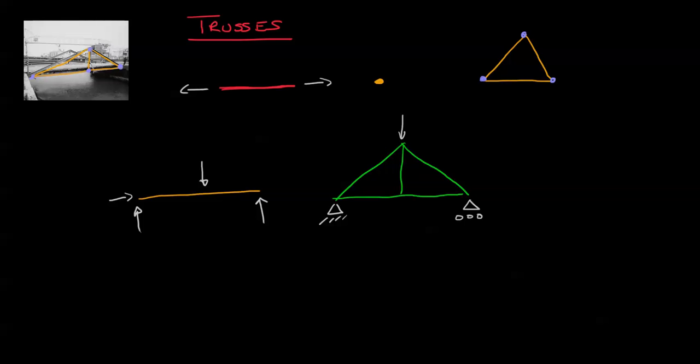And so the first thing you're thinking is, okay, well, you're applying a load. Let's do a free body diagram. So let's do a free body diagram about this point. About that point, we have the load coming in. Okay, and then from one member, we have some force. From the right member, we have some force, and from the bottom member, we have some force. And so we need to balance these out. We sum in the x direction to 0, we sum in the y direction to 0, we figure it out. It's no big deal. We know how to do this.